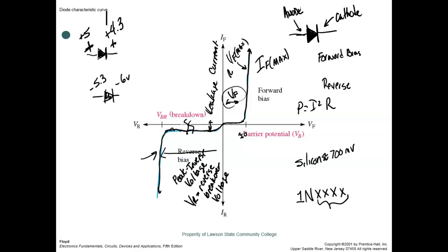So when you buy a diode, you just have to buy a diode. And I think I told you the story. We were building power supplies and it kept burning up resistors, because all the lab says is get a 100 ohm resistor, but they were running like 15 volts, right? You understand? 100 ohms, 15 volts. So that's V squared, 15 squared over R, 100 ohms, and they were using quarter watt resistors. So what was happening, every time they turned their power supply on, it burned the resistor up. And they would come up to me and say, I think something's wrong with my power supply. It keeps burning up resistors.